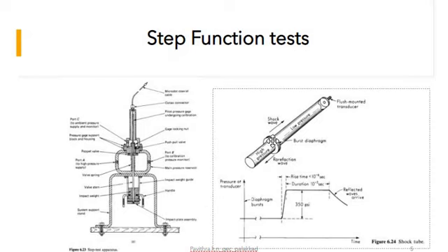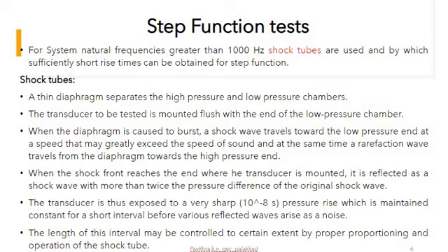That is, when this diaphragm bursts, a shock wave will travel towards this transducer end, and the rarefaction wave will travel towards the high pressure end. So in the system, the transducer is thus exposed to a very sharp pressure rise which is maintained constant for a short interval before various reflected waves arise as noise.